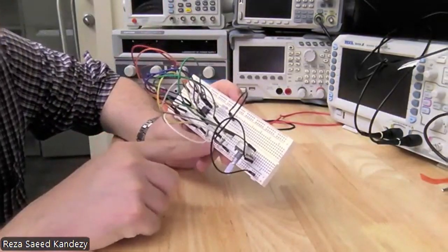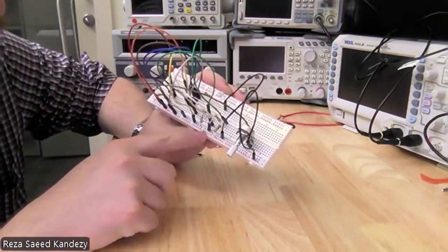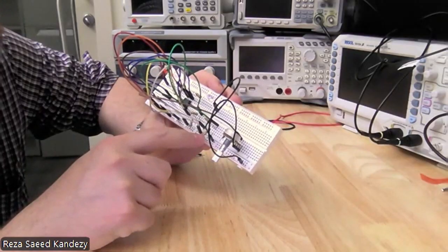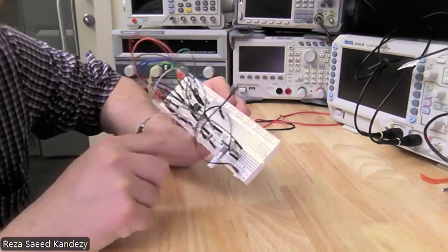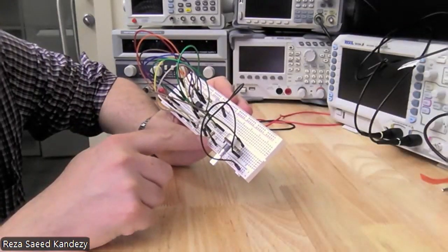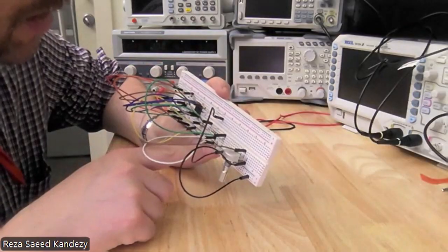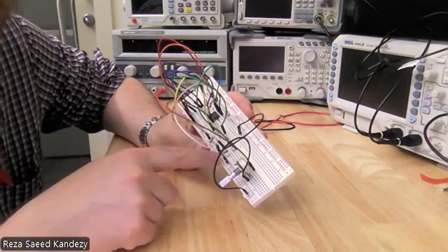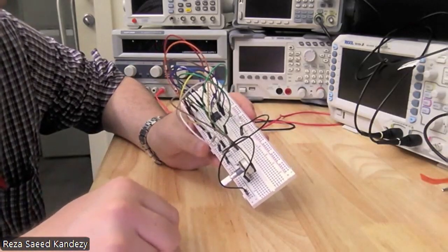So these two are my reference voltages. These are the voltage dividers for the reference voltages. One is 1K, 1K, so it divides the VCC in half. I'm going to set my VCC at 5, so it's going to be 2.5 volts as a reference. It will connect to my yellow LED, meaning it's connected to the warm threshold. So I define my warm threshold as 2.5 volts.